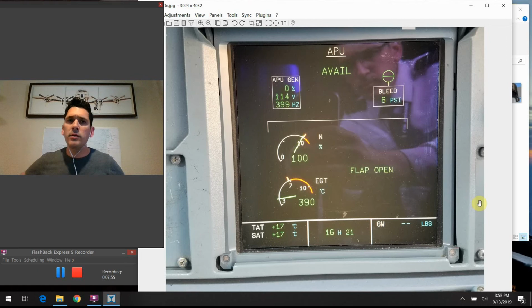But in the process of doing that, you're extracting a little bit of the efficiency and the power capability out of the engine. So there are situations where you want to utilize that extra airflow to keep it going through the engine and not sap that power off by asking the airplane to pressurize or run the pneumatic systems while we're taking off. Let's say we're leaving a high altitude airport on a hot day, or the airplane's very loaded, or we're trying to get off a shorter runway than what we normally have available to us.